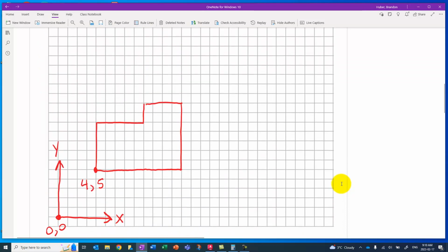We'll use this simple shape as an example. So I've already indicated the origin over here. This is 0 and 0. And I've marked out the first point. So here's our x, 1, 2, 3, 4, and our y is 5. So same as we did the relative coordinates, that first point there is, of course, an absolute coordinate.